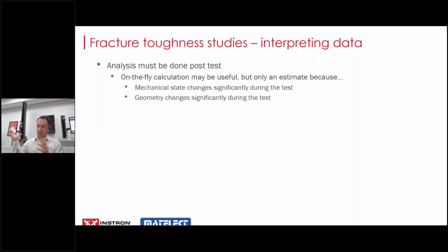I'm afraid I don't have a specimen to hand, or indeed an image here. But when you look at a specimen which has undergone a J1C test, it will often be quite distorted. You will see that it's bent out and that the surfaces of the specimen may be slightly buckled in. So you can see that purely on geometric terms, the shape of the specimen has changed. And you can work out, going back to Ohm's law and the resistivity and geometry relationship, you've changed the resistance around the crack as well. So that's not ideal.